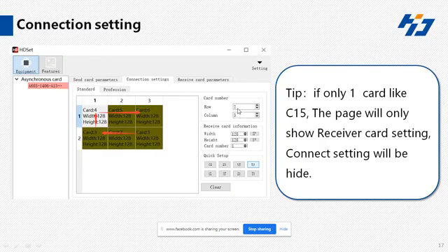So here you can see that in the row there are 2 receiving cards and in the column there are 3, so there are six receiving cards, and for every receiving card you have to justify what the width and what the height is. So once you have told the width and height of each receiving card, you just have to tell the connection of one receiving card to another, meaning how the LAN cable is connected with each other.